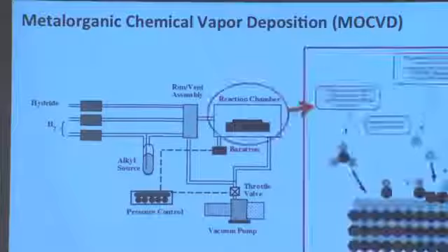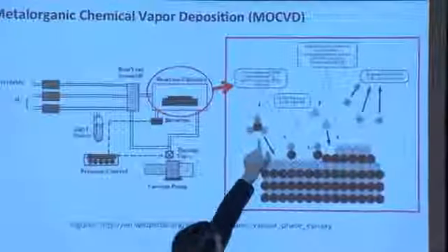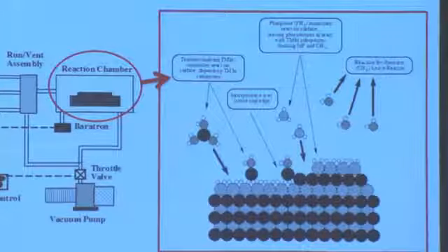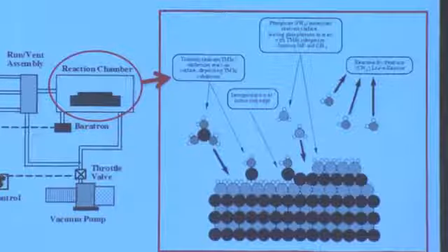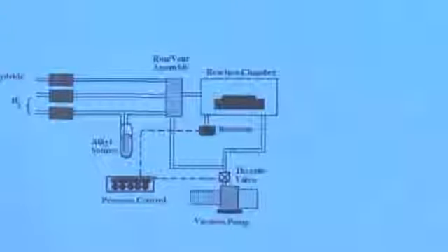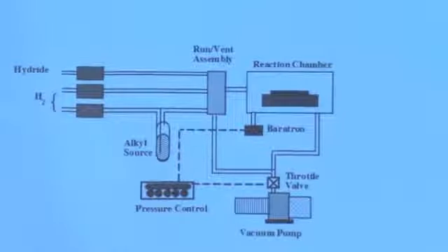The reason it's metal-organic is because we typically have a metal, like this representing the indium right here, and then little organic compounds on the outside. Those are methyl groups, the little gray and the two white dots. Those represent 3 methyl groups around the indium, so trimethylindium. And what we do is we flow these molecules into our reaction chamber and control the temperature gradients inside in such a way to have those molecules deposit on the surface, leaving the indium behind, or the metal behind, and the reaction products float away out the back.